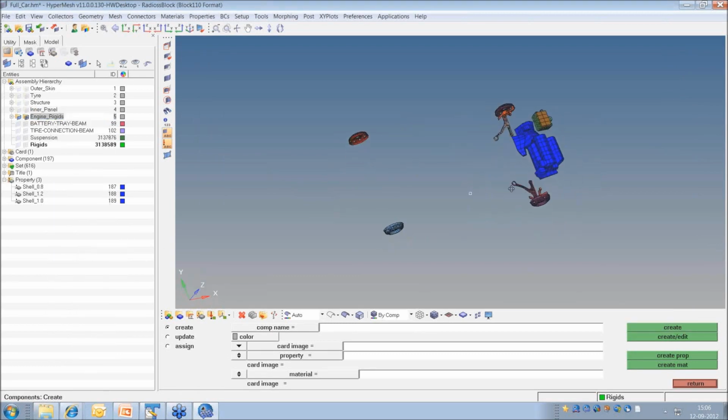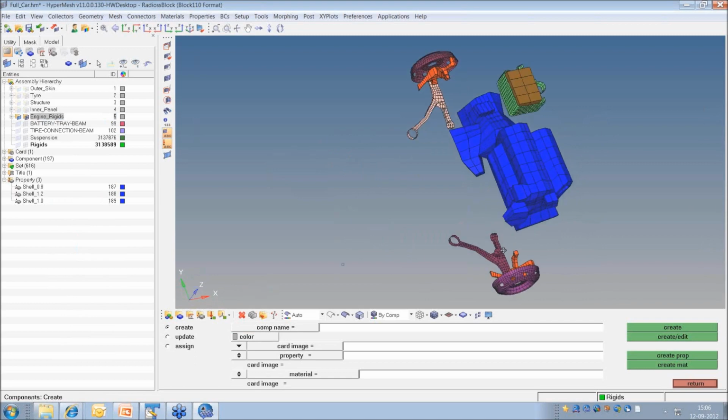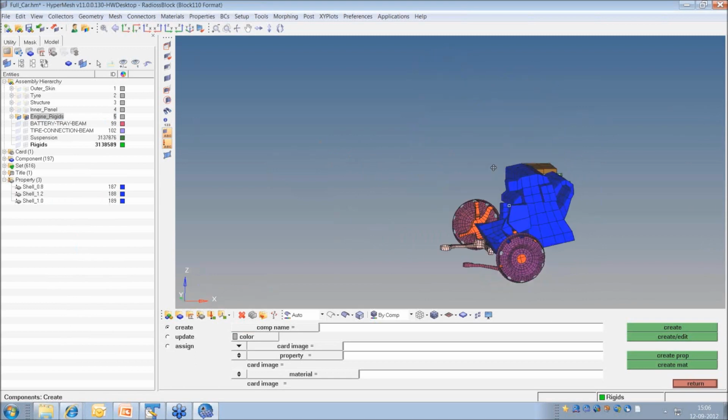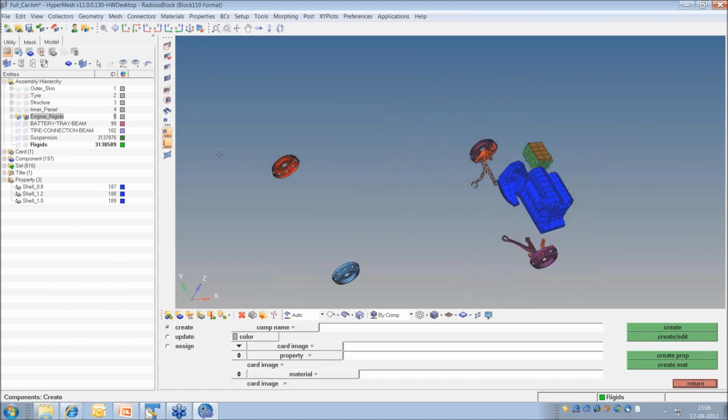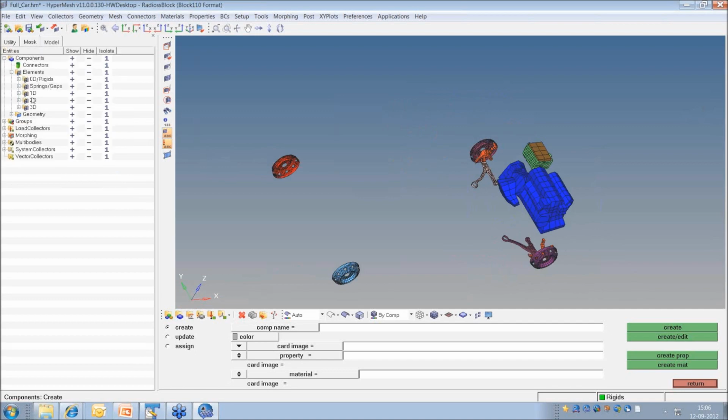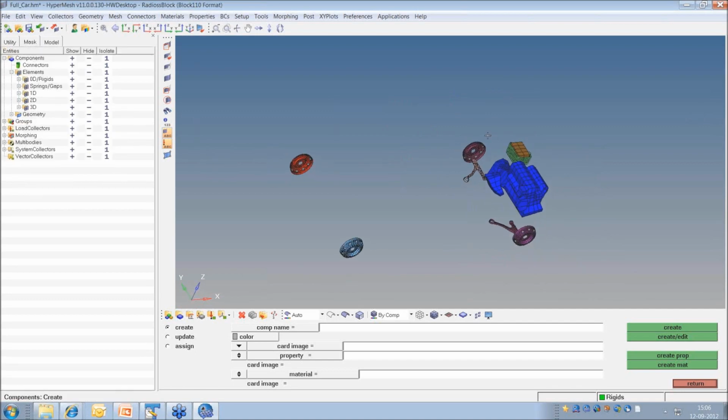Okay, so here I have some discrepancies in the sense that I also have some solid parts, which I want to neglect. So again I'll go to mask, 3D's mask. Okay. So all these things I'll push for 1 mm because anyway I'll be making this material rigid. These are shells, so they require a property, but I'll be making them rigid at a later stage.